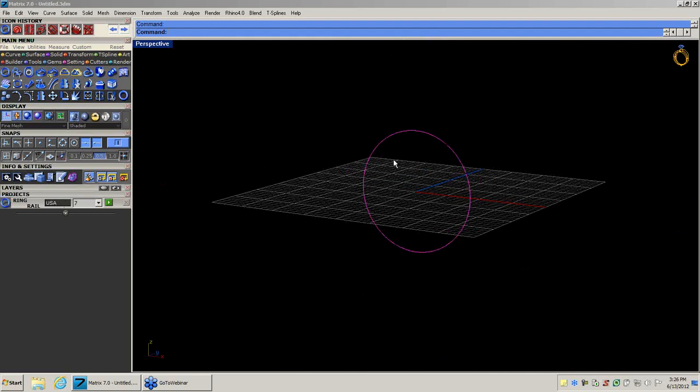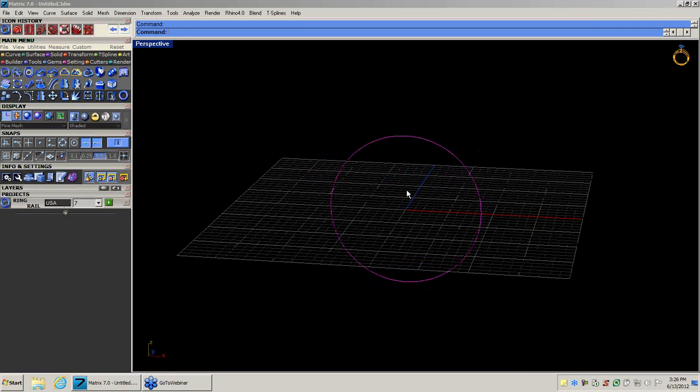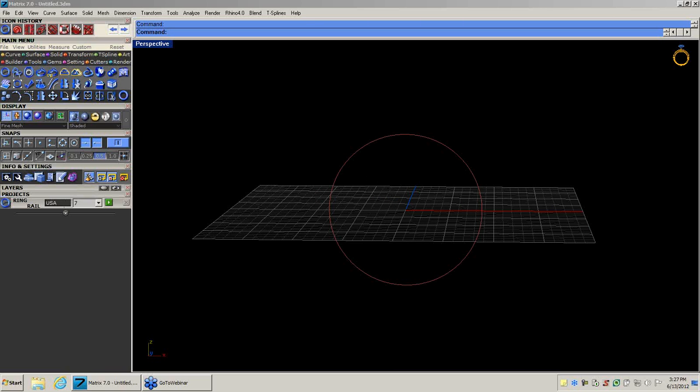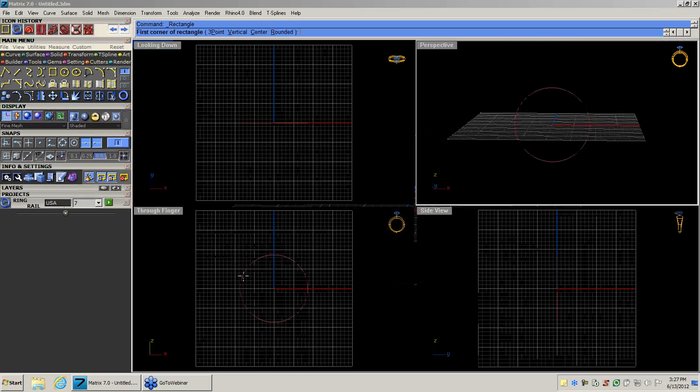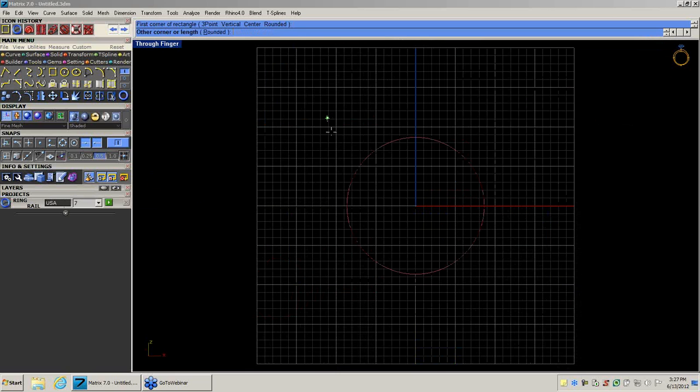I'm going to double click on this. We're going to take a look at it. If I didn't have this builder in here, if I was using just Rhino as a standalone system, I would have to know the circumference of this finger size, figure that out, divide it by pi, and then figure out the radius from there. We do it with a click of a button. Now, personally, I like to work inside of a constraint is what I call it. And so if I went to the yellow section over here, the curve section, as an example, and if I wanted to build a square ring, I might just come in here and draw a square around the outside of my finger hole.